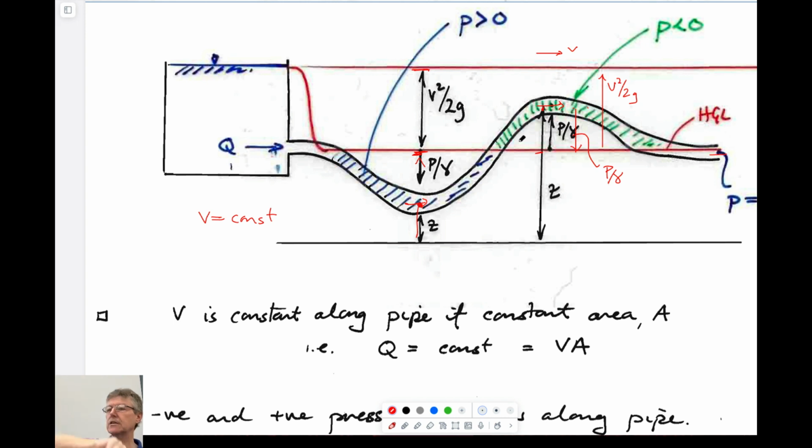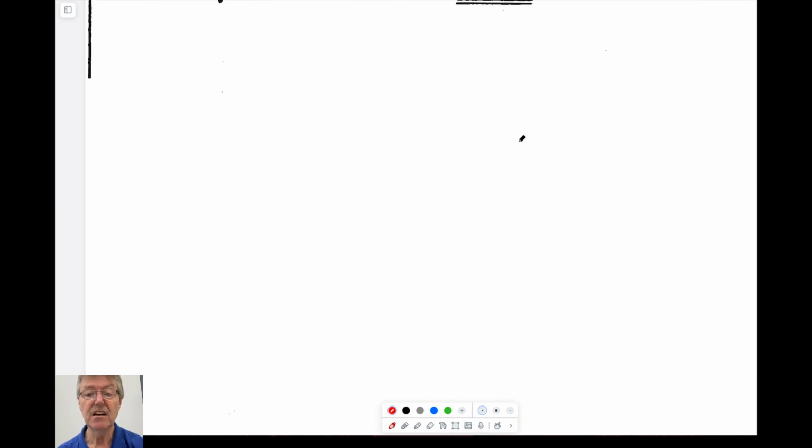And so what it would do is it tries to flow like a siphon, right? It has to flow in a siphon. If it goes through absolute zero pressure, it will cavitate, it will bring the air out of the water, and it will collect it in a little jar up here, comes back down, it's de-aired water, and you can use it in your experiment. So that's one way to do it.